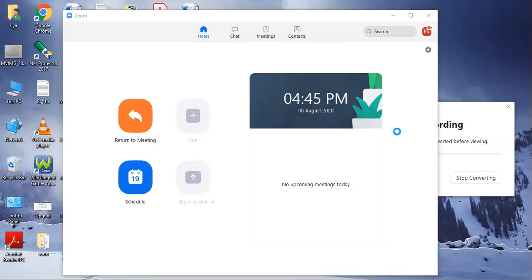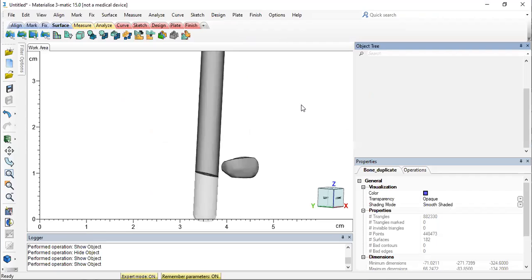Now to attach it to the extension surface, you can use two options. Either you can just create a connecting cylinder between the two, or you can use something called a cylindrical loft. Cylindrical loft is basically a fancier version of creating a link between two different components. So let me show you both ways.